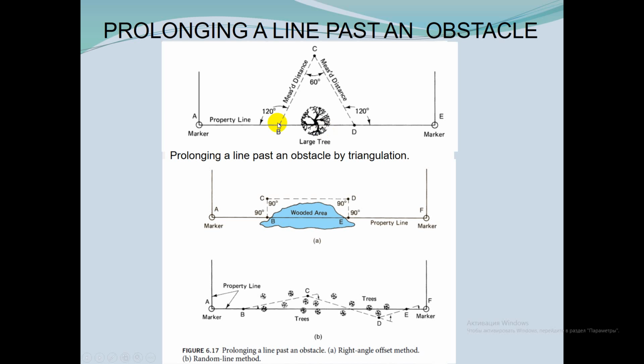Also, the optimal equilateral figure cannot always be constructed due to topographic constraints, and angles as small as 20 degrees are acceptable for many surveys.